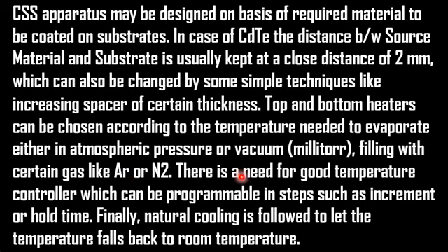There is a need for a good temperature controller which can be programmable in steps, such as an increment in a time or a hold time. Okay, so student, please note that the closed space sublimation system also requires a temperature controller. What does the temperature controller do? It increases the temperature of the reaction chamber with the passage of time.